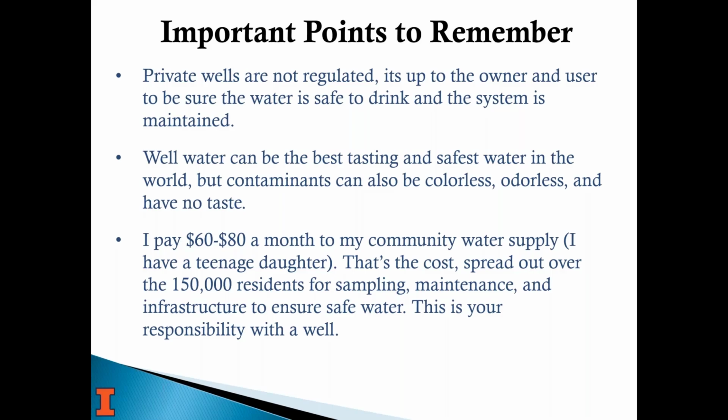And as a well owner, that's your responsibility. To ensure safe water and to make sure that your pump doesn't fail, for instance, if you're pumping sand, eventually that's going to tear up a pipe and it's going to start leaking. Or if the water is corrosive, it'll start degrading some kinds of pipe. All those things matter, and so you need to understand that as a well owner.